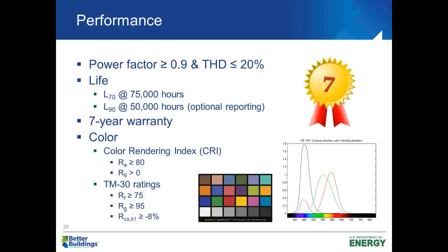While I agree with you that some manufacturers may be extrapolating based on their extensive knowledge of their own equipment, which they know better than anyone else, we have documented manufacturers who are claiming, using both TM21 and LM80 data sets under a certain temperature, over 72,000 hours. Going back to the other person's question, yes, TM21 does limit the extrapolation to 6 times the life. However, if the chip data is longer than that, then that could push it out. So if it's 12,000 hours of chip data and 6 times, that's 72,000 hours. So we are seeing some manufacturers out there.